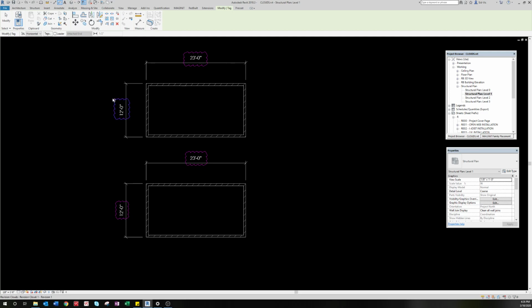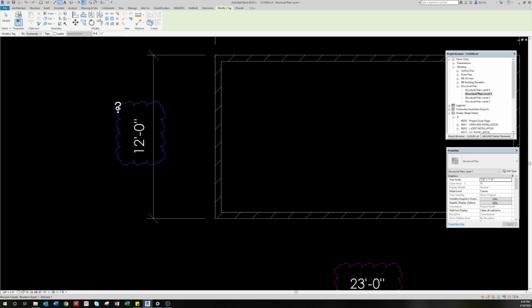As you hover over that cloud, you're going to see this question mark pop in. Now I'm going to move that out of the way. This is by default in the template a starting point for us. So if you're clouding something and you want to add a note, say AOR to verify, you can simply type that in and click away, and there you go. You've actually got a comment that is associated, a tag, but it's a comment tag associated to this cloud.